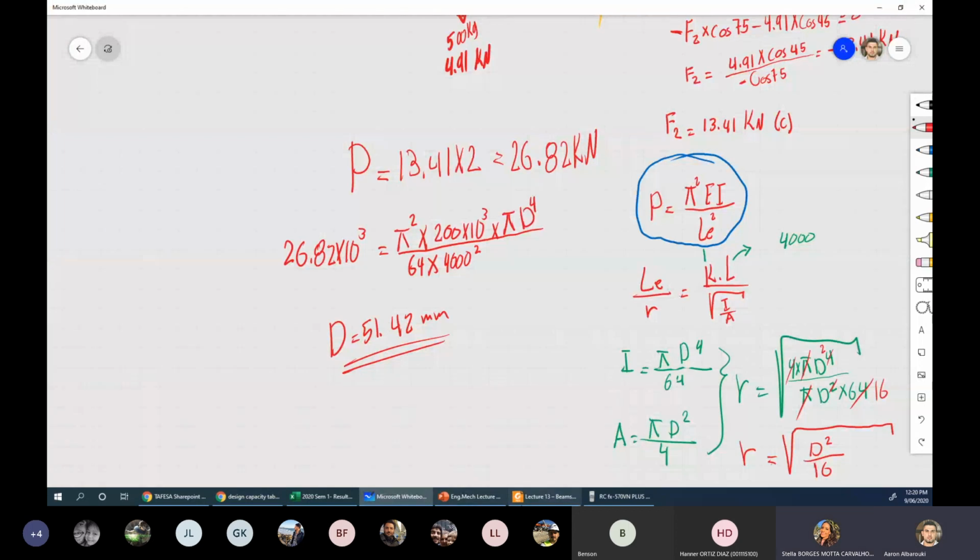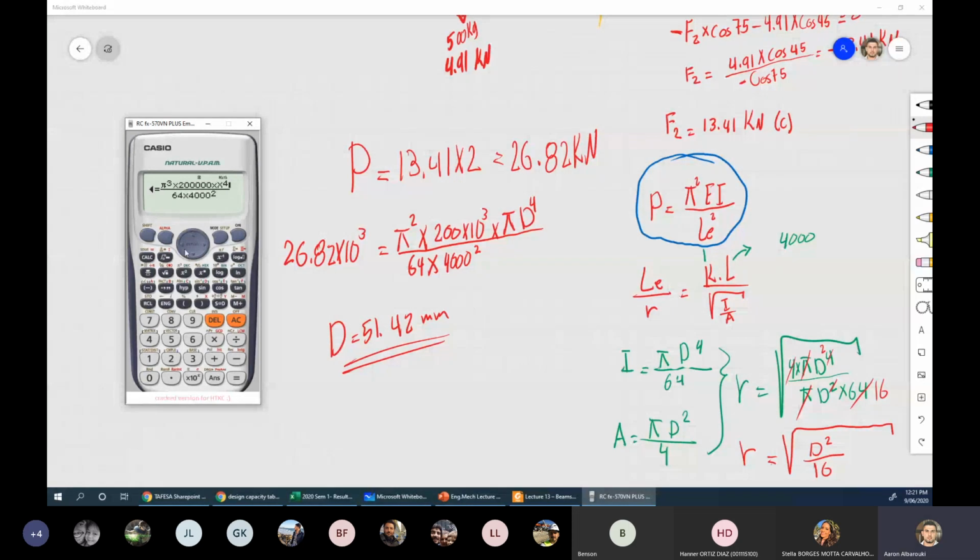This was my initial question because I saw some exercises on the internet, especially on YouTube, where they explain how to solve the problems, and in all the examples they use 200 times 10 to the power of 9. If, let's say, I put here to the power of 9, just so I can go with you, okay? So that would be another 3 zeros. What do you mean? Why more than that? So, guys, keep an eye. Did they use meter at the bottom? If they used meter, that's why. I'm using millimeter at the bottom here.